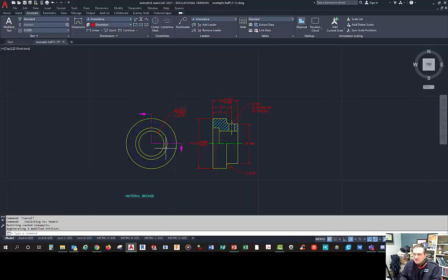The first thing I would do is draw the part, scale it on the viewport, right? Then go to the correct layer, hopefully you think about it. Or if you go over here to annotate, you can tell it that you want to use dimension as your dimensioning layer, because that's what I have set up, and mine's red.